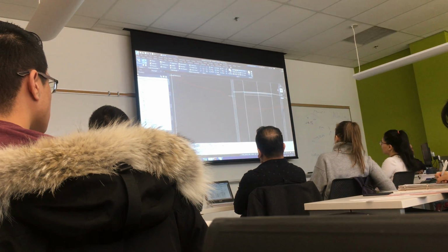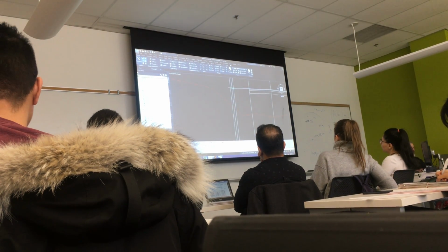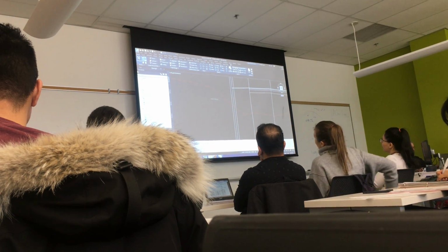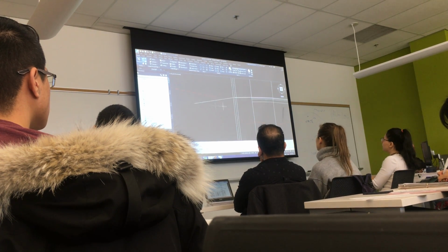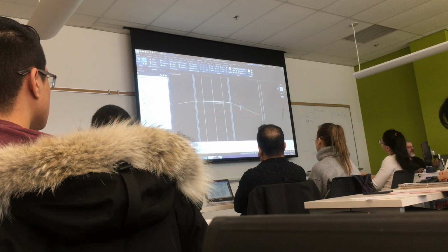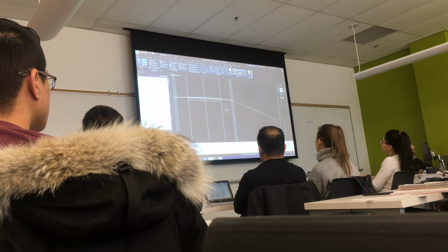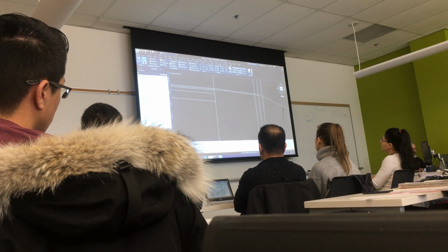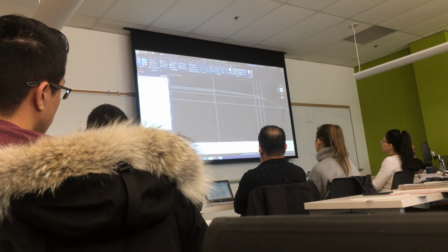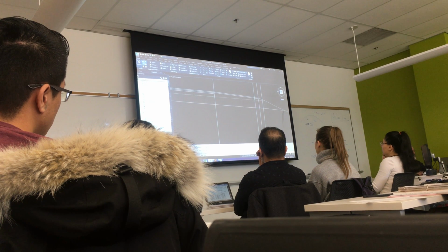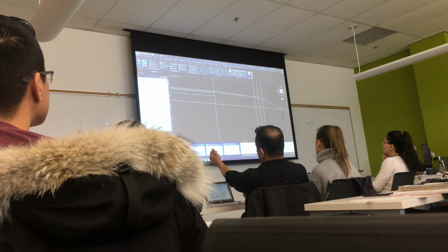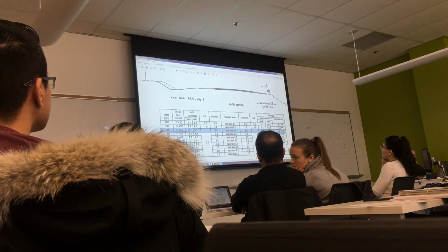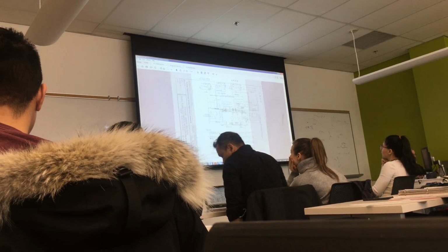So let me try. Let's see what's happening on this side. I'm going to draw a line from this end point. I'm going to go 6. I'm going to go down 1. I'm going to close it for these. And there's my line. So how do I know whether it's a cut or a fill? I'm going to extend to the slope this layer and this layer. Whoops. Yeah, this layer. I forgot to copy. I need my 6%, right? I already screwed myself up. Let's go back to here. Forgot to make a copy of this.